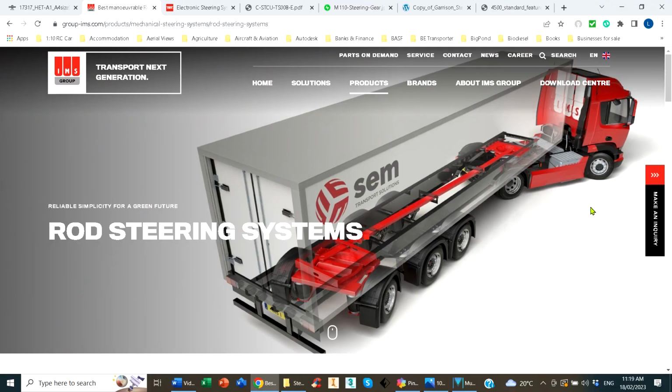We don't see it much in Australia, although it is coming, but a lot of semi-trailer trailers have rear steer, and we'll show you an example. Here's what this company has called rod steering, and they're using the pivoting around the kingpin to control the steering of the rear axle. Now that's essentially wagon steering, and that's a simple, basic arrangement that helps a whole semi-trailer move more manoeuvrably.